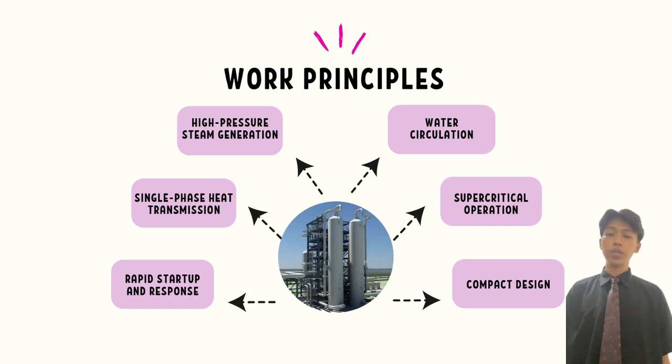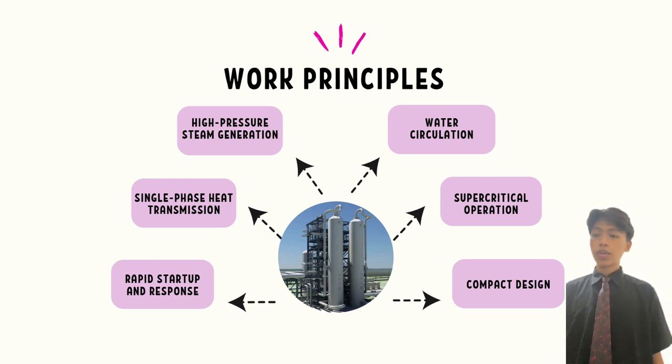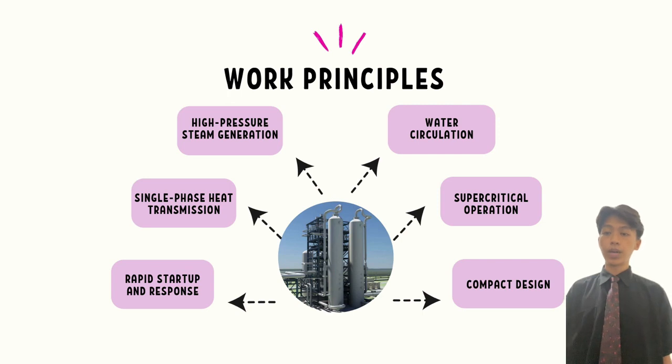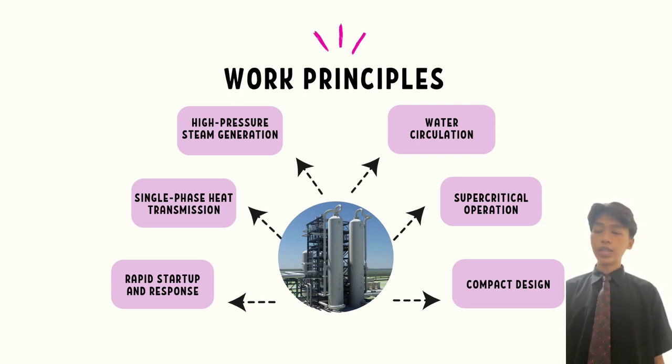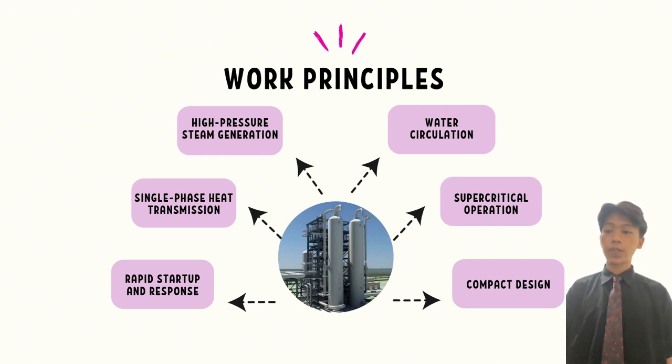Third, the Benson boiler uses single-phase heat transmission, as opposed to conventional boiler, which use steam and water in distinct phases like liquid and vapor. Fourth, supercritical operation. By operating above the critical point of water, the Benson boiler avoids the liquid to vapor phase change.